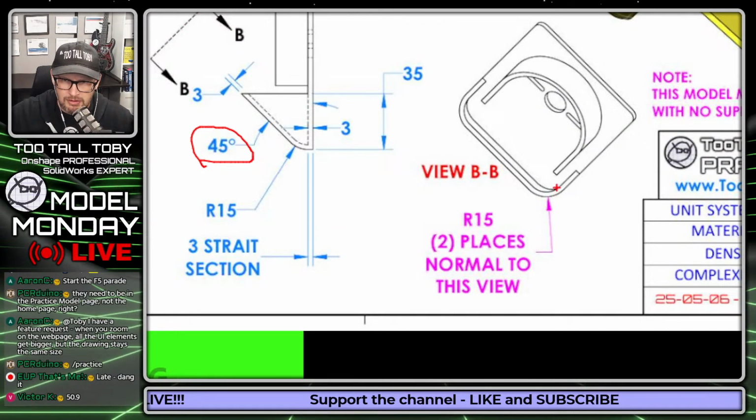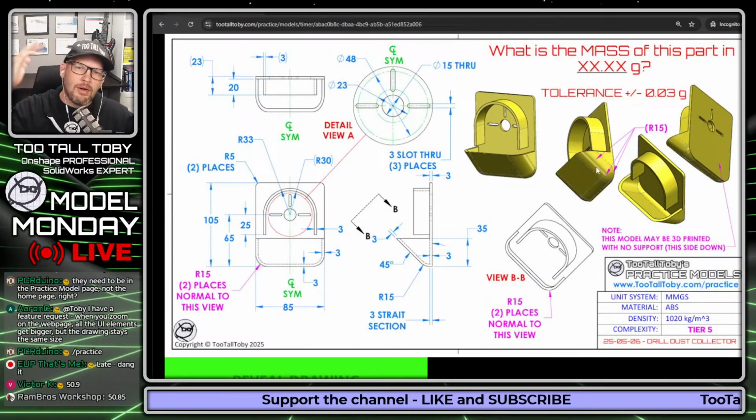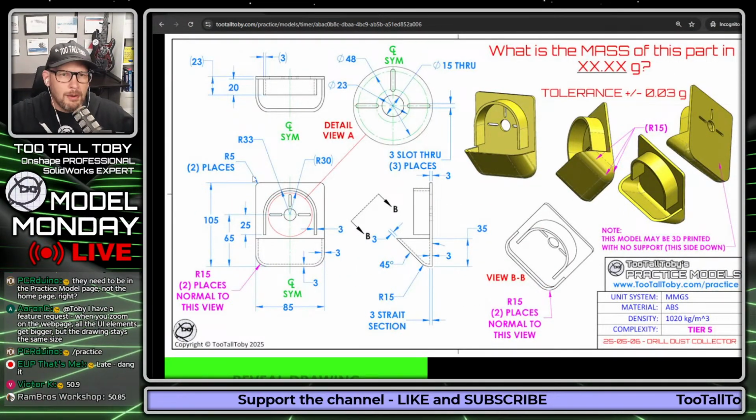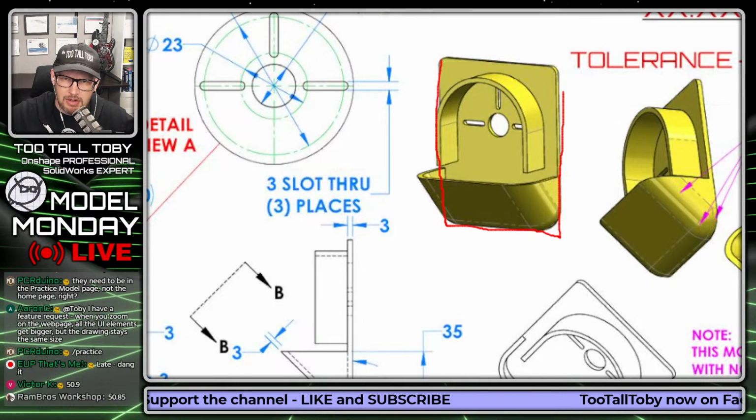So we got our 45 degrees here, and then we've got this radius here. And that's where you definitely need to do a little bit of planning. There's part of me that thinks the best way to start this model might be to just create this shape here, this flat back shape, and then once I create that shape, add in those fillets in that first sketch.